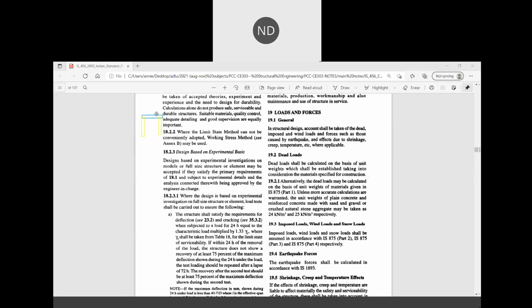Just for an example, I'm showing you these three members, but there will be other members also, as you know, like the slab, the plaster on it, the plaster paint, and the flooring. These are nothing but your dead loads. These are known as your dead loads.